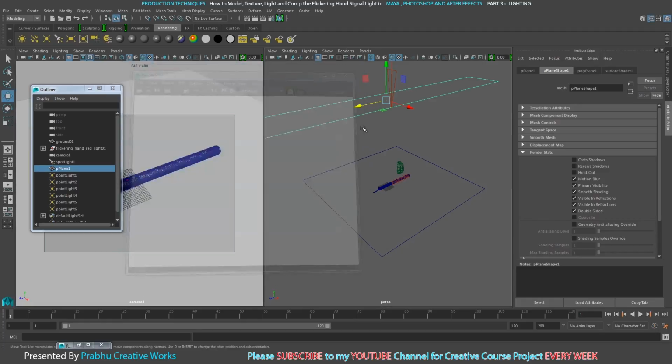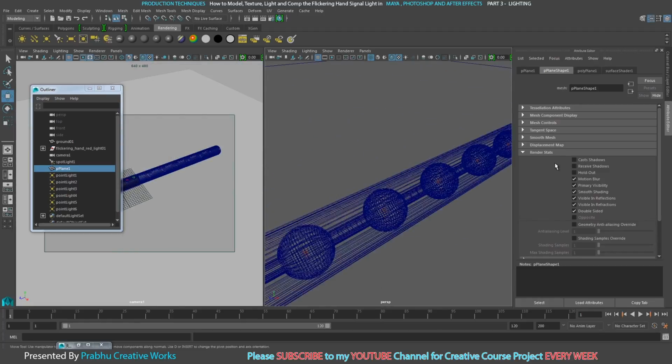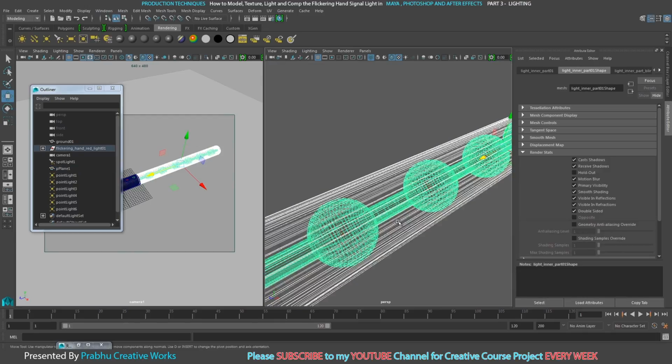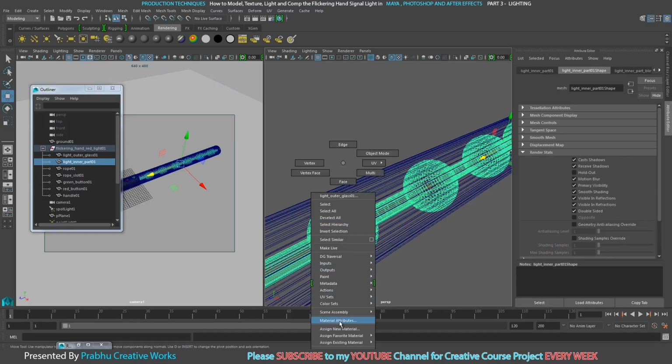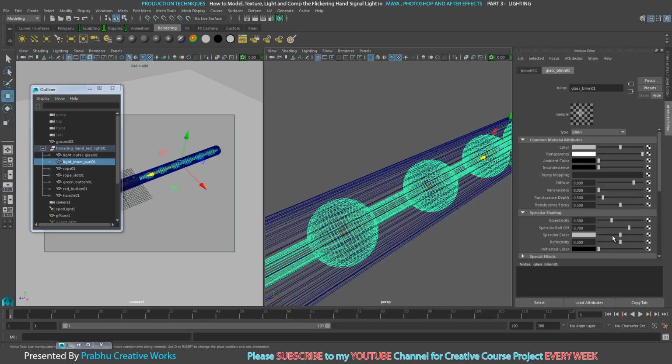So now go over here and select the inner material. Go to the flickering hand red light group, select this light inner part, right click and choose material attributes. I want to reduce specular and reflectivity for this object.